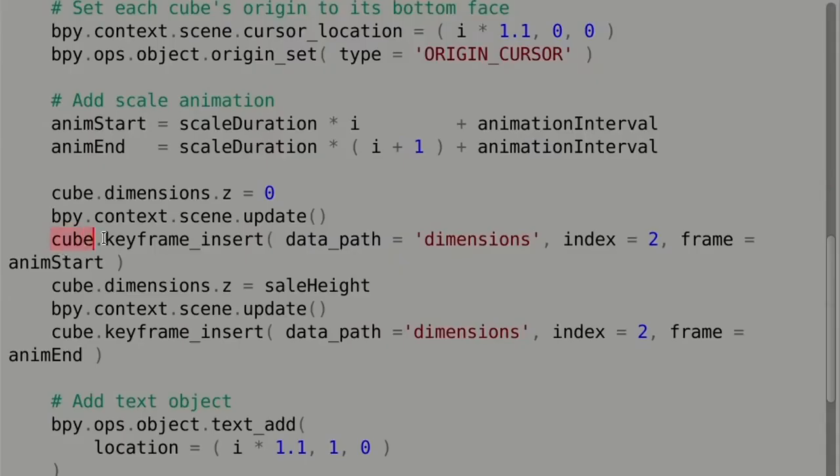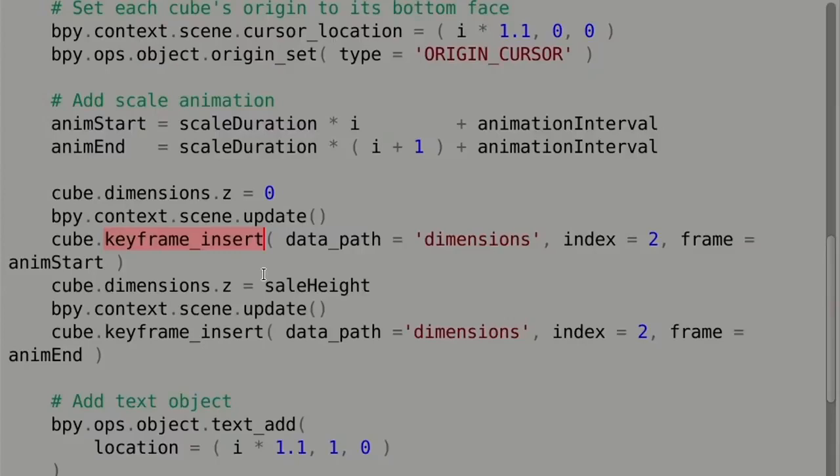Another thing that you can do is generate animations in Blender programmatically. I'm actually doing something that is called inserting a keyframe. Keyframes are a way to animate that doesn't require you to set values for each and every frame in your animation. Instead of starting and setting this pose and then slightly different and slightly different, you have one pose and keyframe it, and then keyframe the second pose, and you have an interpolation that automatically moves between the two. That's a keyframe.